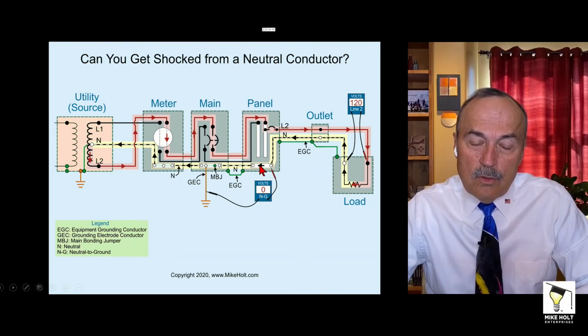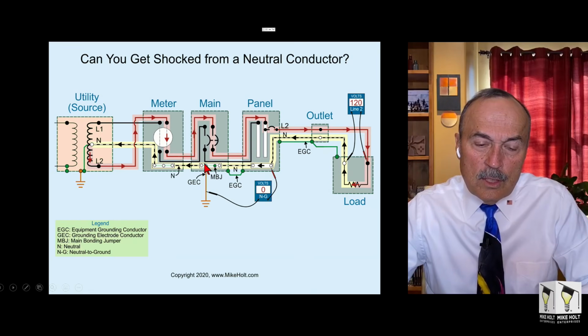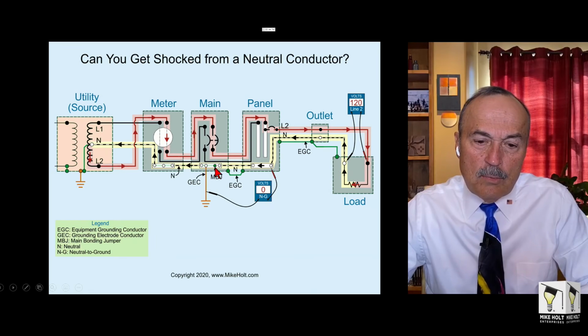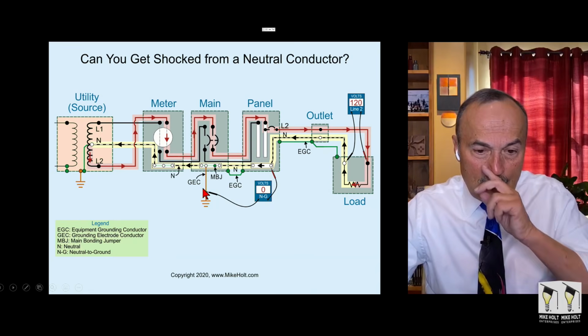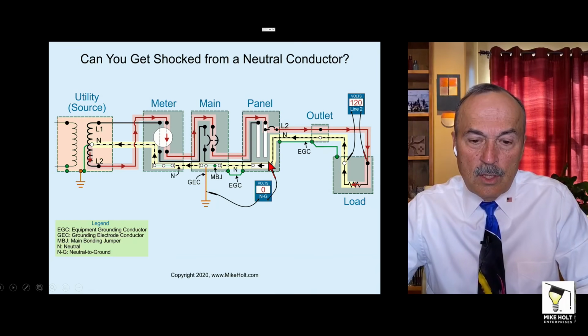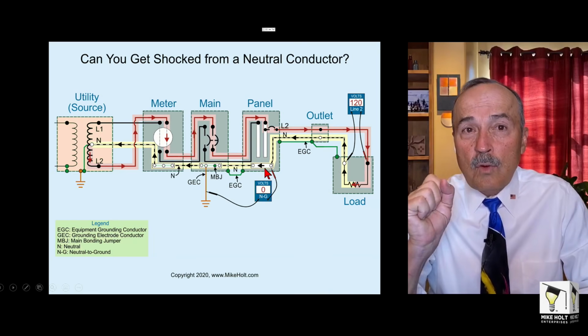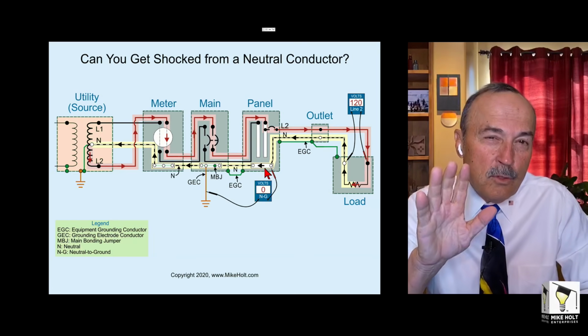Then over here at the neutral, this neutral is also connected to the earth. Well, this is at 0 potential. This neutral here is at 0 potential. So when you take a neutral to the earth, we probably should not show it to the grounding electrode, but let's just show it to the earth. Standing on the earth, touching the neutral, you can have what? 0 volts.